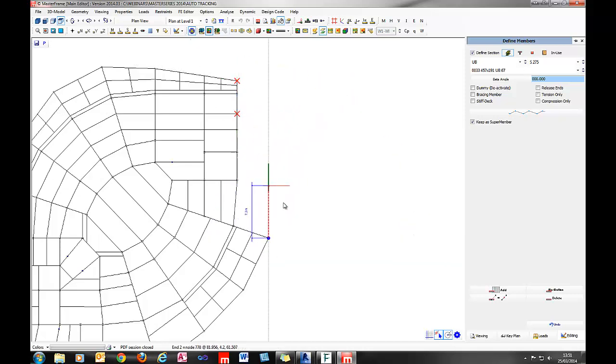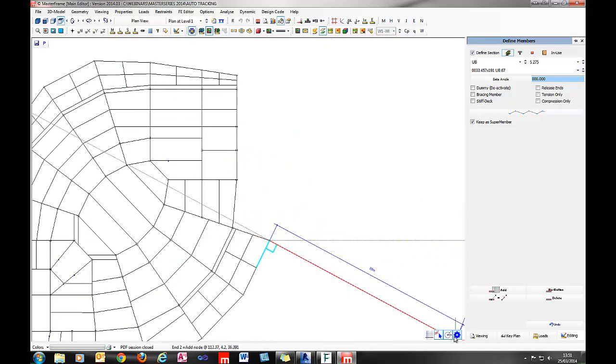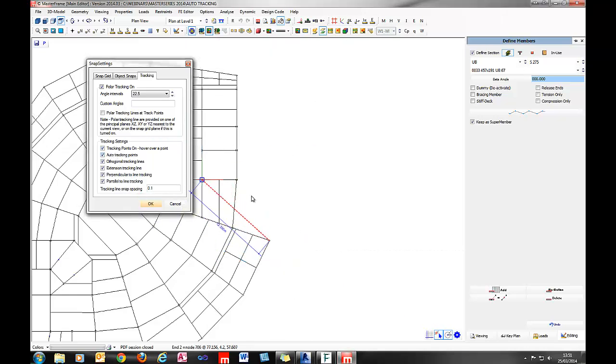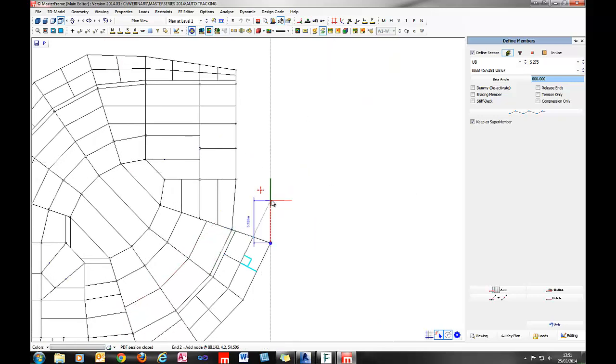Now, for drawing something very quickly, to align itself with all of those beams, I could spend more than a few seconds picking up those tracking points. However, rather than always having to do that, we now have the ability to turn on something called auto tracking, which is on by default. What the auto tracking does is look at where you're snapping and choose automatic points in the proximity of where you are. So now you can see those points.